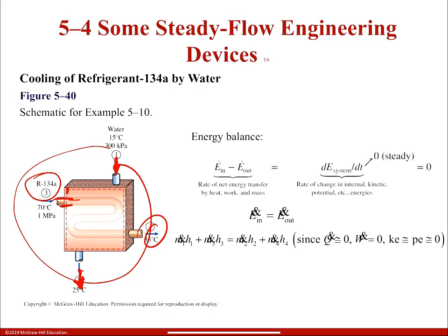So if I take this as my system, the question you need to ask yourself is, is the heat crossing those boundaries? The answer is no. And that's why heat is equal to 0. But let's say your system is going to be the pipe. Then that will be different, because we are transferring heat from and to the two fluids, right? And when that happens, the heat will cross these boundaries, and therefore you have to take into consideration the heat